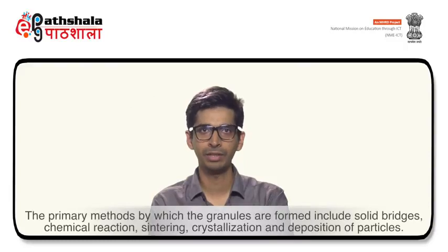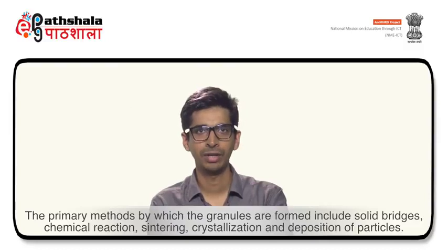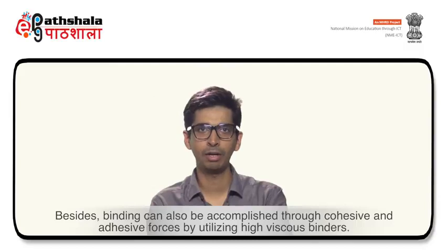The primary methods by which the granules are formed include solid bridges, chemical reaction, sintering, crystallization and deposition of particles. Besides, binding can also be accomplished through cohesive and adhesive force by utilizing highly viscous binders.